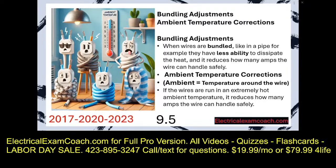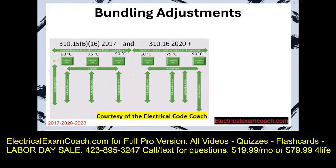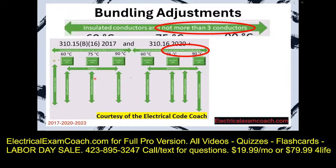Let's get to it. Let's dive into bundling adjustments. Let's take a look at our primary ampacity table. I want you to turn there now. And these values down below this table are true if, well, the question is if what? If you look at the paragraph above the table, the one that I said we would come back and look at later, it's got some parameters there. It says, hey, these are the ampacities of these conductors if, and the first if that we're going to look at is if there are not more than 3 current carrying conductors inside of a cable, pipe, or even buried in the earth together.